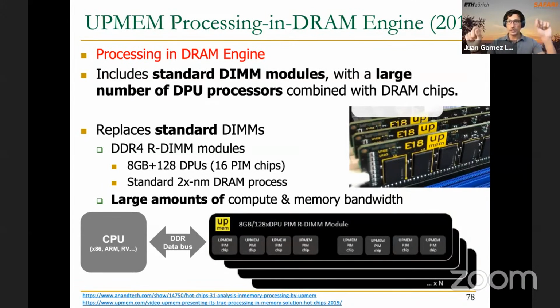I have this memory bus connecting the CPU and the memory, they are very far from each other. Every time that I need to go to memory, I'm going to spend a lot of cycles, and a lot of energy. So why don't we put some processing capability inside the memory, right? This is an old idea, but for different reasons, technology challenges, no one built, or at least no one commercialized such an architecture. So 2 years ago, the French company UpMem